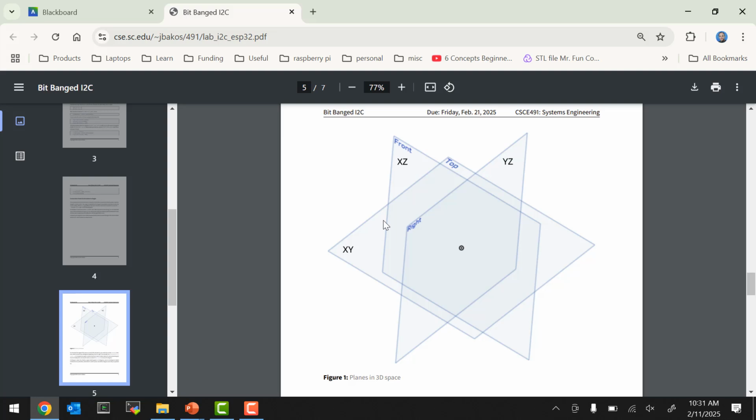I guess negative 1 g, right? It would be negative 1. Okay. So the scale is plus or minus 2 g's, and it's expressed over 16 bits, right? So what that means is that, remember, it's signed. A 16-bit signed number has a range of negative 32,000 to positive 32,000, negative 32K to positive 32K. And that's meant to represent negative 2 to positive 2.